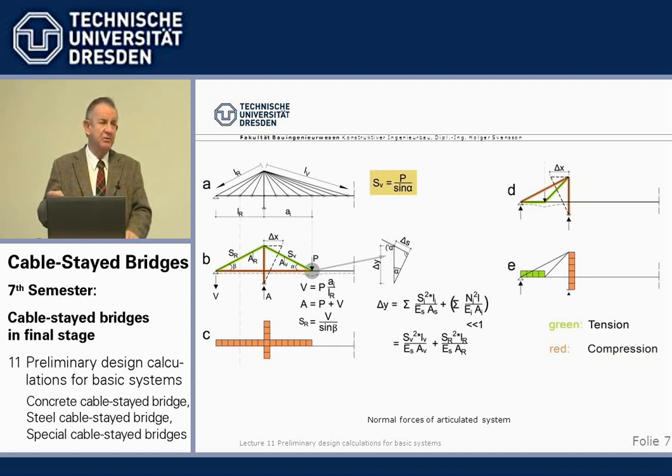So we take away the moment capacity of the beam, and we take away the fixation here and introduce a hinge here.